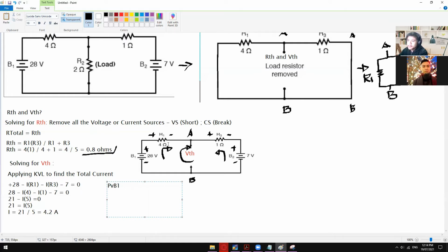So after passing through this R1 right here, we have to get the original voltage source value minus the voltage drop, okay, across R1. Okay. So in here, V1 is of course 28 minus VR1. Okay, so of course we have to solve for the VR1.